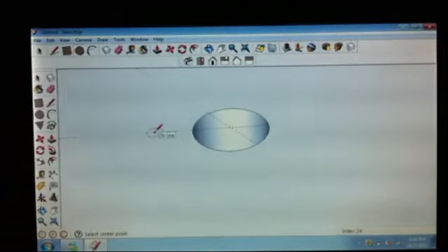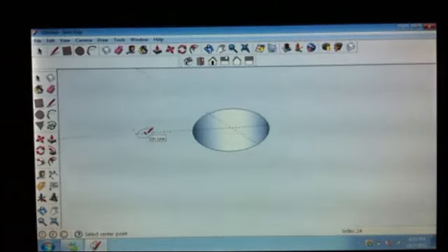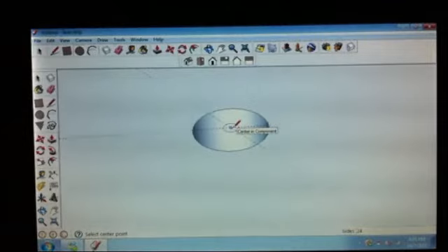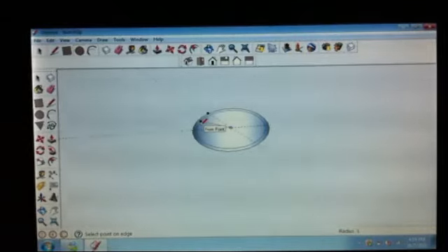In this case, you see it's on the surface of component. That means now the circle is drawing on the surface of component. But once you get into this part here, because it's hollow, the computer can't recognize at what surface you want to draw the circle. So all you need to do is put it at the surface here. You can see the blue color. You press the shift key and then you move it down here. Then the circle will still be blue color, and then you start to draw the circle. In this case, same thing, the rod is 1.5 in radius.